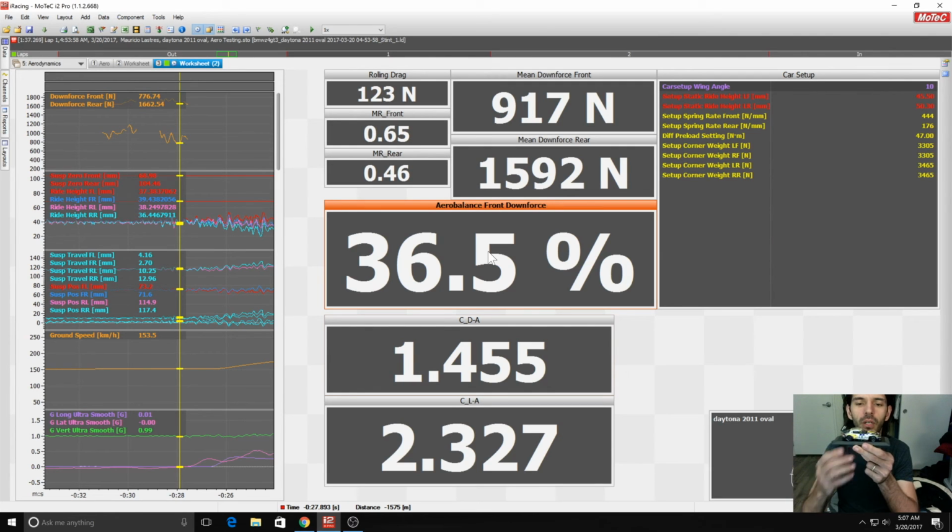And sometimes you'll have a crossover where maybe you have a center of gravity that's pretty low, and maybe just a little bit more forward. But then you'll have a center of pressure that's a little bit further back, and your balance is not directly related. I mean, it's related to your center of gravity, but there's other factors that are also involved. But say that you have mechanical balance, where you have more front grip than rear grip, and if you could put that as a percentage based on front to rear, you could have it biased to the front, where you have a lot more mechanical grip in the front, but then you have your center of pressure way back.